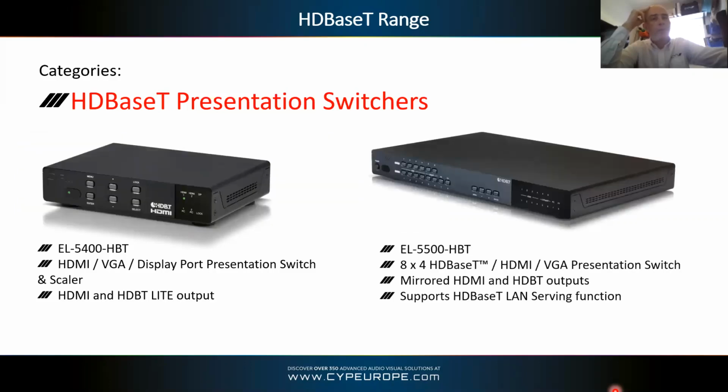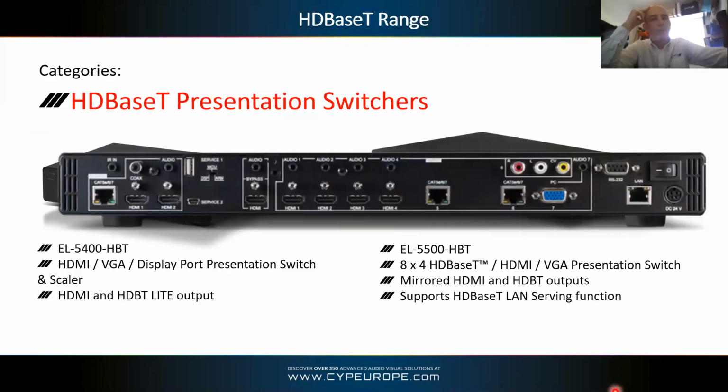Above that, you've then got the EL-5500, which is more inputs, more outputs. We'll have a quick look at the back of that, but you can see there HDMI inputs, HDBaseT inputs, so you can come in remotely from a further distance away, and then HDMI and CAT outputs as well for HDBaseT out. So again, just a bit more versatility there, isn't it, Kev, if you need more inputs and outputs effectively. Yeah, and it's the ability to bring those remote sources into a centralized location, which is mirrored on a few of our larger presentation switches. That's really useful. Great stuff.